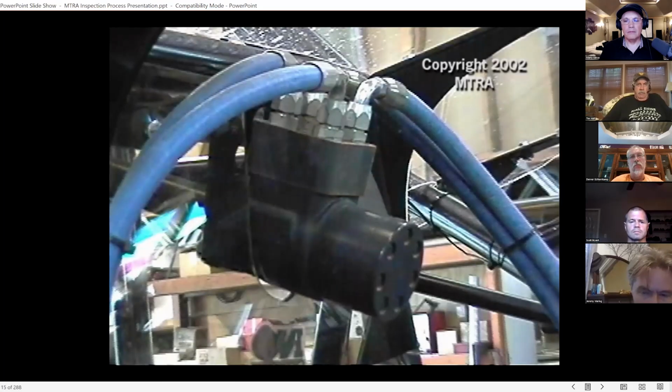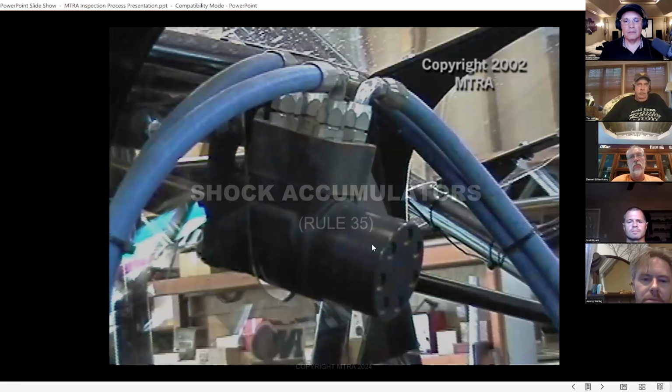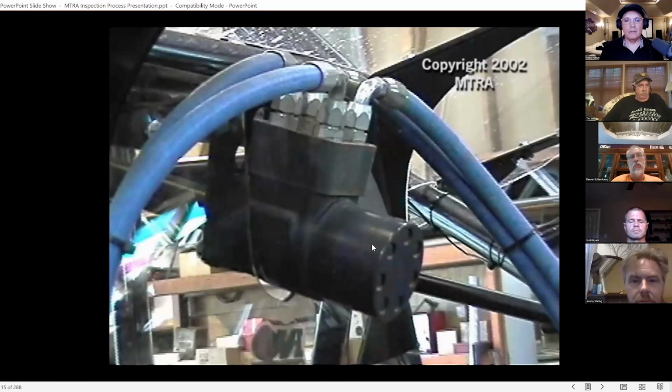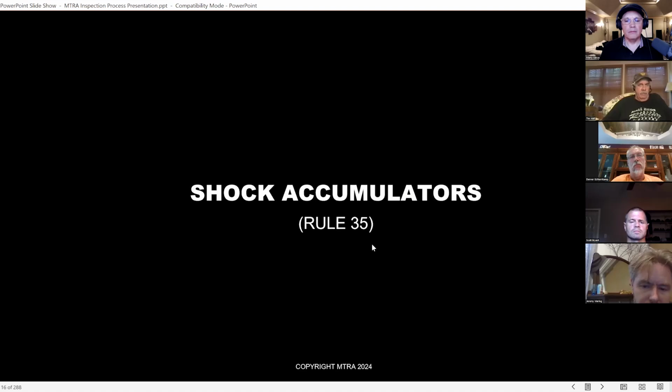So they've saved numerous drivers over the years. They're a little bit that kind that bolts the orbital lights on there. The big square there that the hoses are coming out of, that's the valve. That's probably the easiest to find. But there are the kind that are in line, they might be mounted on an axle or 4-link bars anywhere. But you can see the hoses go to them, through them, and then down to the cylinders. And that's what we're looking for. The accumulators mounted securely and away from the tires.